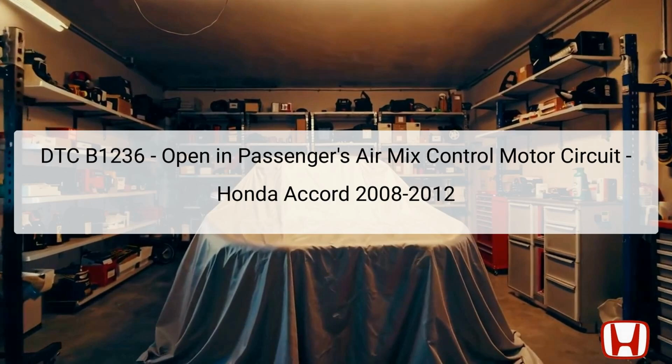The DTC B1236 indicates a specific error concerning the passenger's air mix control motor circuit in Honda Accord models from 2008 to 2012. This diagnostic trouble code, DTC, suggests that there is an open circuit affecting the proper operation of the air mix control motor, crucial for regulating the temperature of the air entering the cabin.